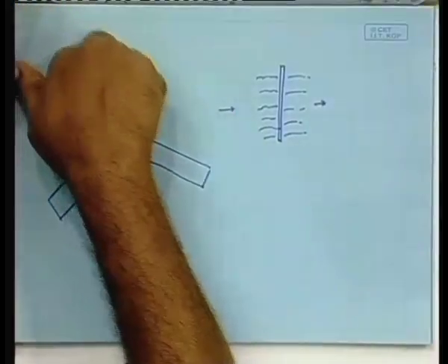So, it is clear that the optimal choice of the number of blades should be dictated by the consideration that the time taken by the disturbed wind to pass through and the time taken for one blade to come into the position of the other blade should be almost the same. Clear? Slightly larger, but almost the same.